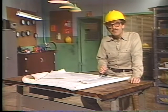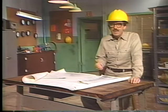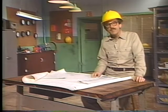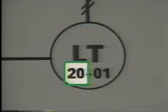The instrument symbols in a P&ID also often include numbers. These numbers have specific meanings as well. Let's look at our simplified P&ID to see what the numbers are for. The first numbers in the instrument symbol typically identify the control system that the instrument is in.